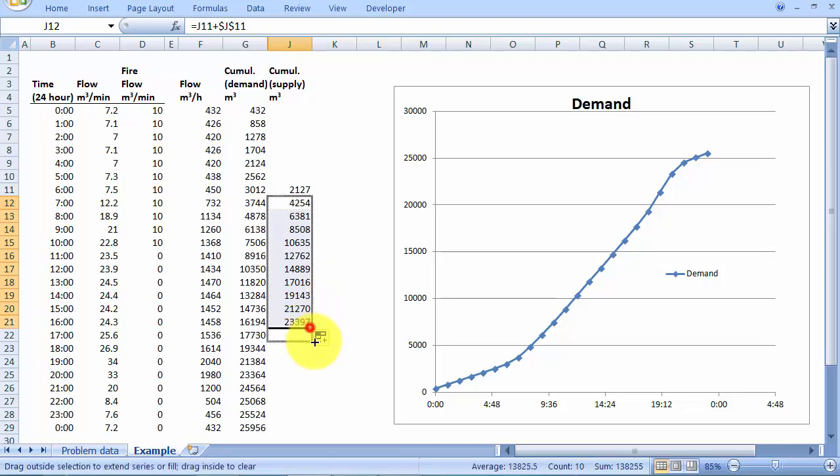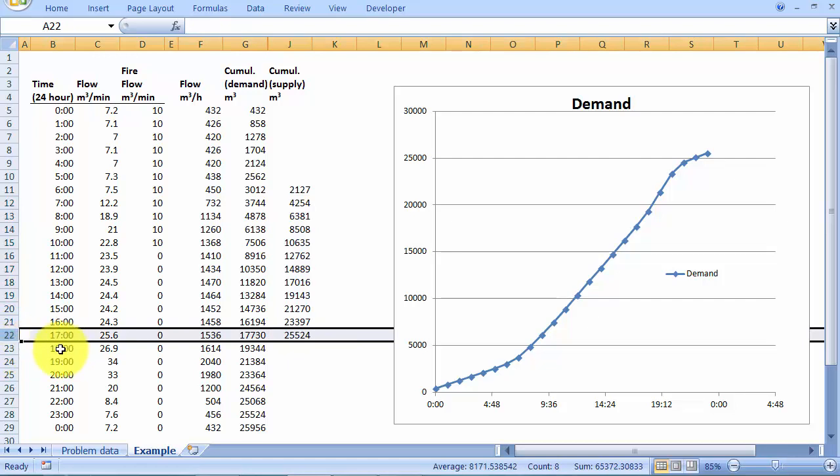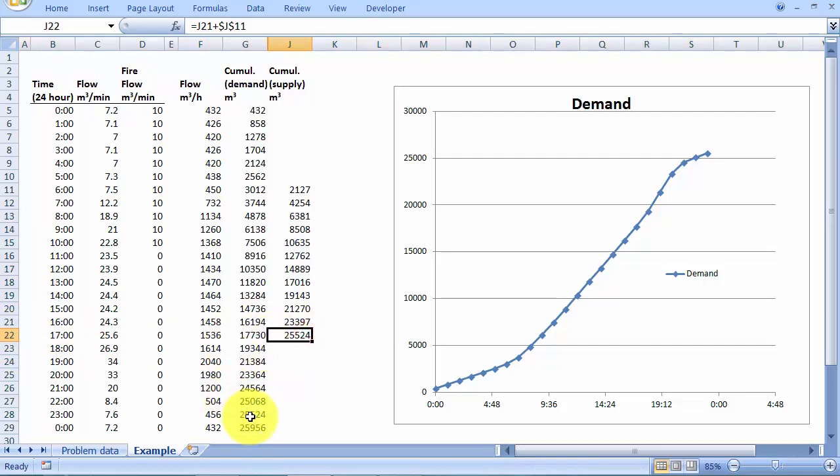until after a few hours, just before we switch the pumps off at 6 o'clock, we have our required total daily flow. So you can see there now that these two cells, the flow in 24 hours, match the pumping rate in 24 hours. And all of the other flows, this one's just equal there. So our cumulative rate from 0 to 6 a.m. is just 0, and after 6 p.m. is still our maximum value.